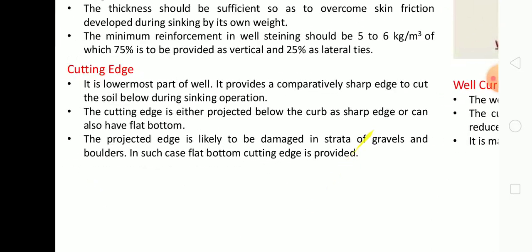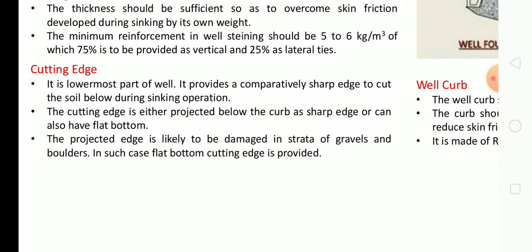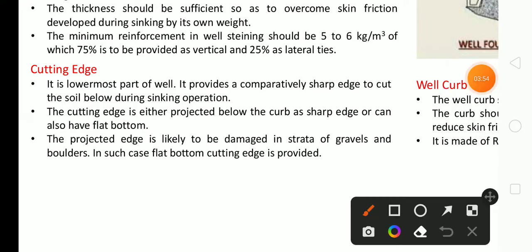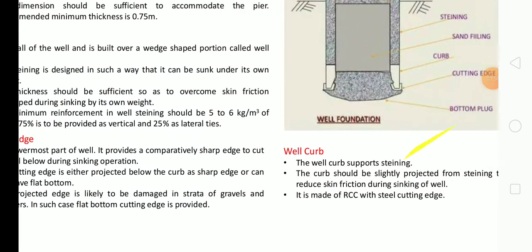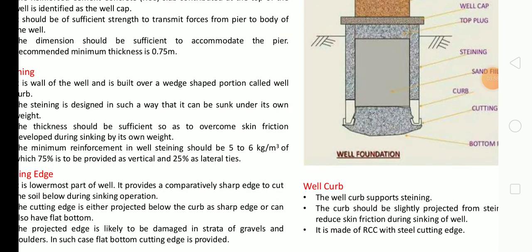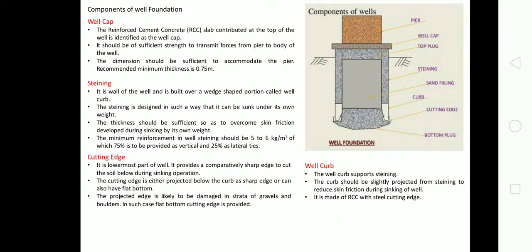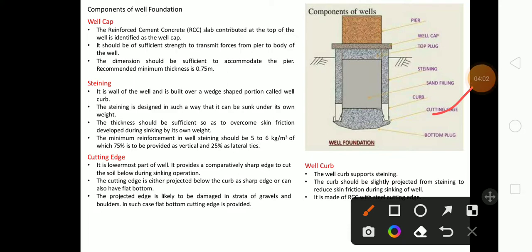Next one is the cutting edge. It is the lowermost part of the well foundation. You can also see it in the figure, this is the cutting edge. It is the outermost part of the well. It provides a comparatively sharp edge to cut the soil below during the sinking operation.